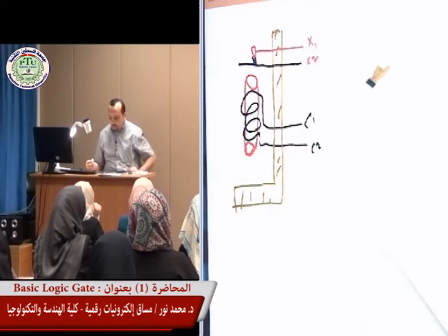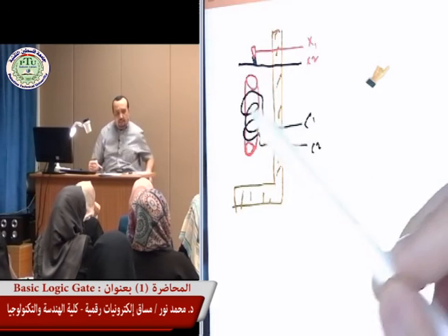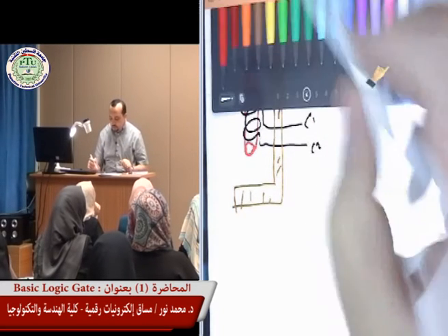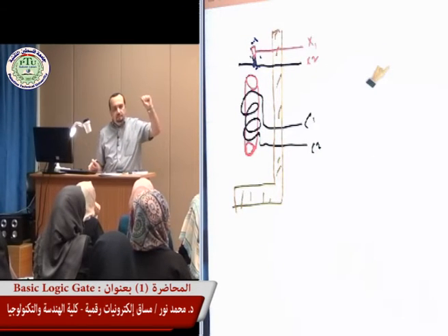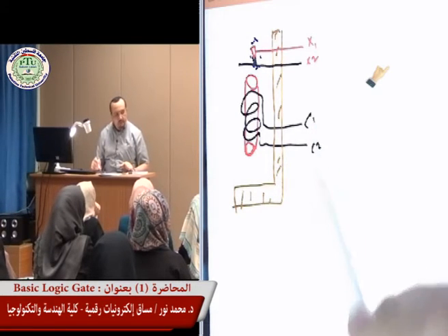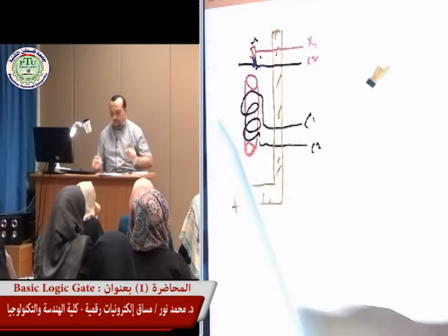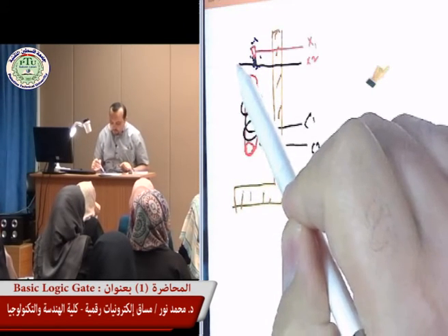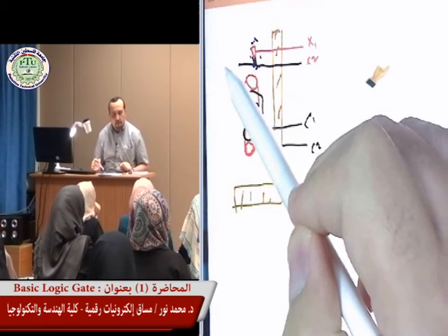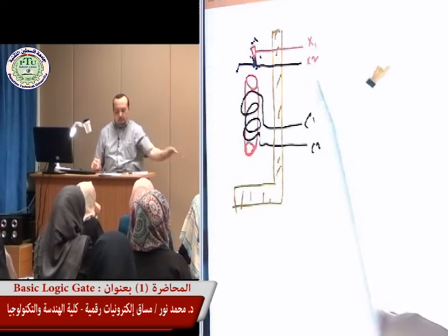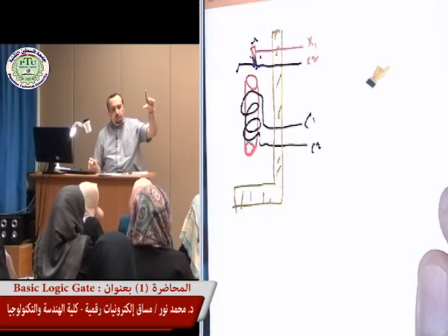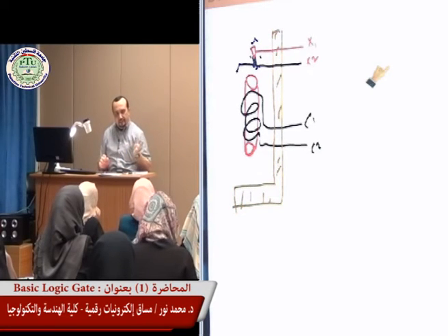As you see here, in C1 and C2, if we have V0, there is no applied voltage, so basically the two points around this area are in contact. Now if I apply a voltage across C1, C2, this extended rod or wire, if you want to think about it, this one here, will bend down. So what happened to the contacts? It will open.